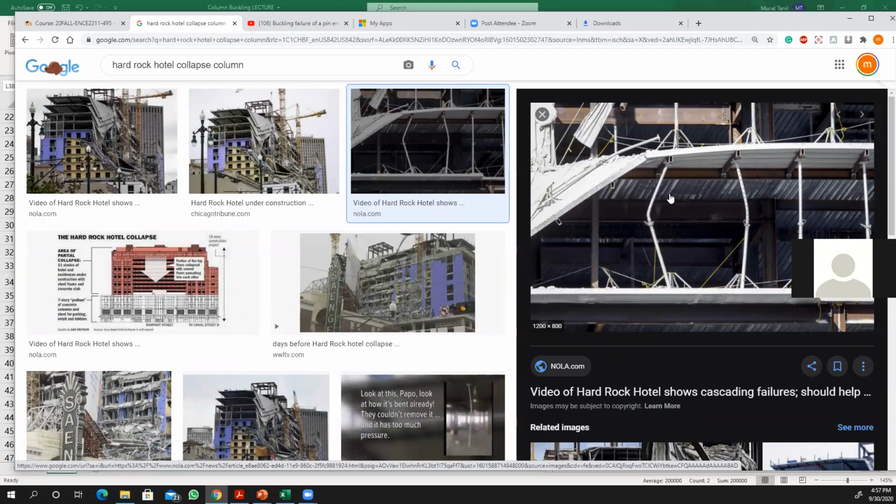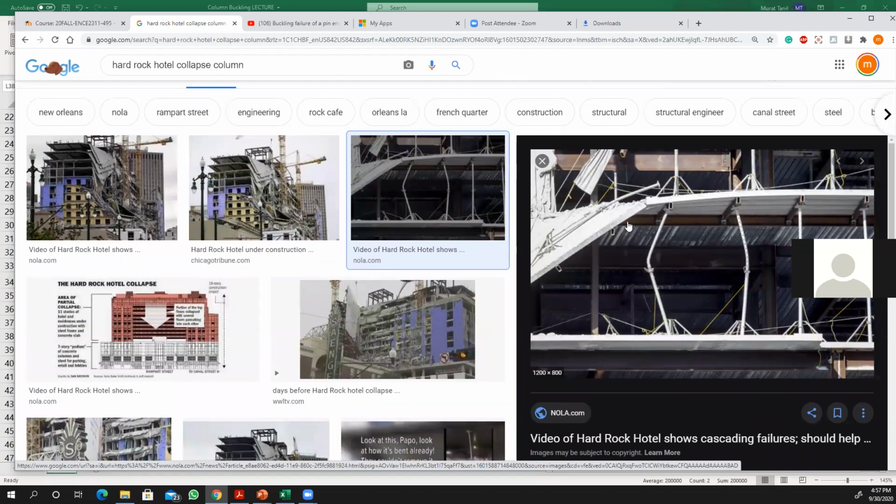But these are temporary shorings that buckle, and the only purpose of the temporary shoring is to handle the load coming from the fresh concrete, because it takes 28 days for concrete to bear 4,000 psi stress, and it takes 3 to 4 days to bear its own weight. So for the 4 days timeline, you should have exterior support to carry the load coming from the fresh concrete.